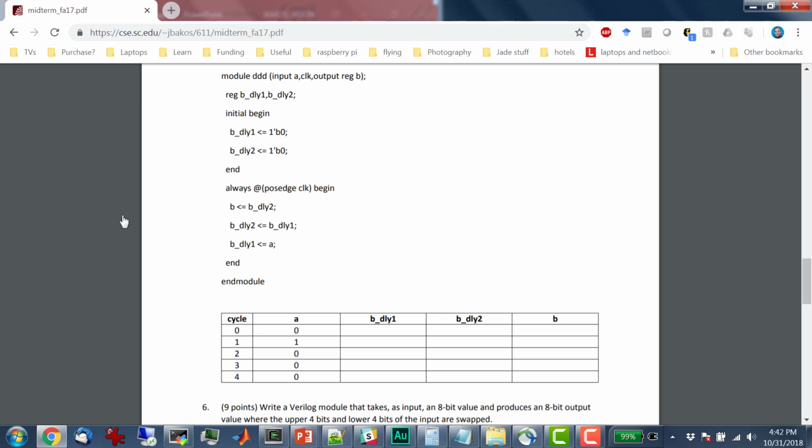We could create a serial to parallel converter out of this too. Like if you shift these bits of A down into these slots, 3 cycles, then we could read them all 3 at the same time. You know what I mean? So we could shift in 1 bit at a time, but then read out 3 bits at a time. Every 3rd cycle we could shift out, create a serial to parallel converter.